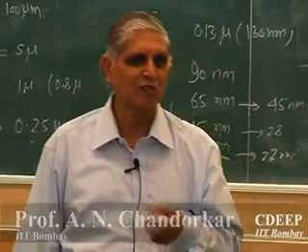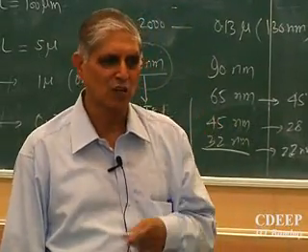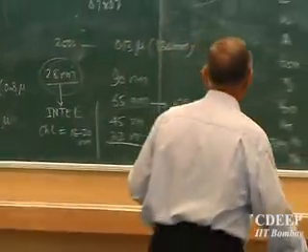And if I keep my voltage constant, then I say constant voltage scaling, the first thing that will change is what? Fields, because voltage is higher, other things reduce. And as field rises, the device physics changes, because the fields are high now. We'll see next time what are called short channel effects, what things can go wrong if I reduce. Okay. See you then tomorrow.